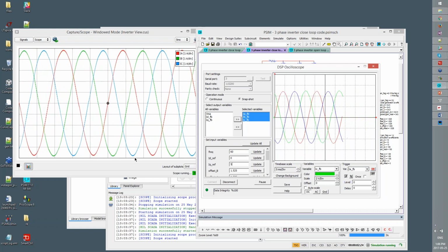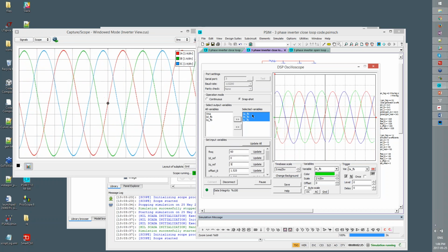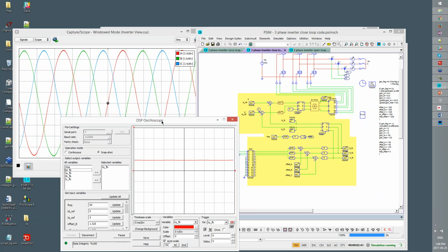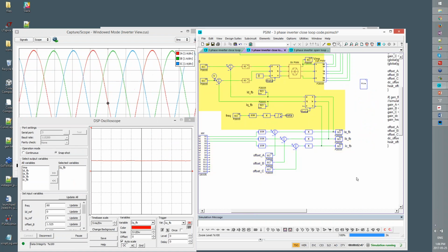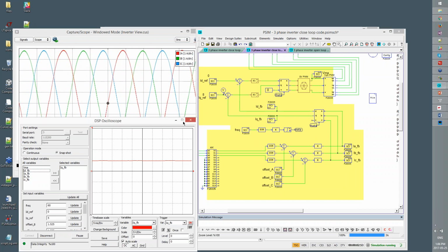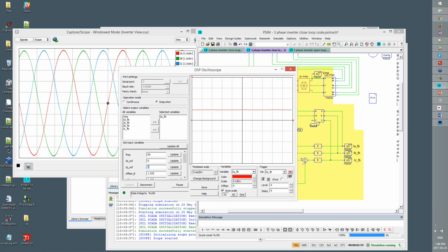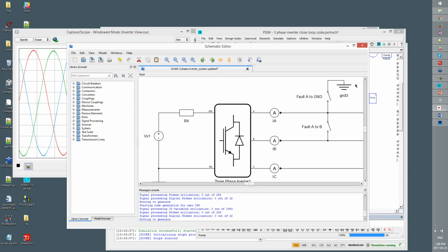Again, we're running closed loop here, at least I think we're running closed loop. Let me pull up IQ. So this is the IQ feedback value. Whenever there's a signal we want to look at, all we need to do is put one of these SCI blocks down, and then we can map it back and pick it up in the scope here. So here's the IQ reference value. As I move IQ around, oh, this is the wrong load. Let me switch loads.